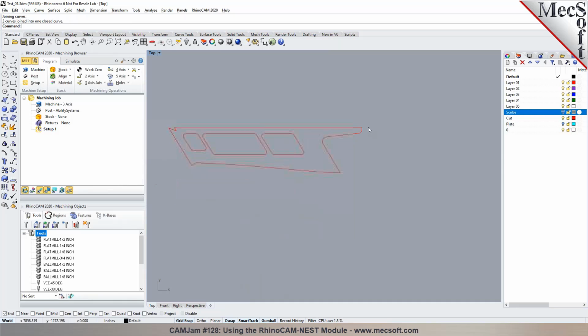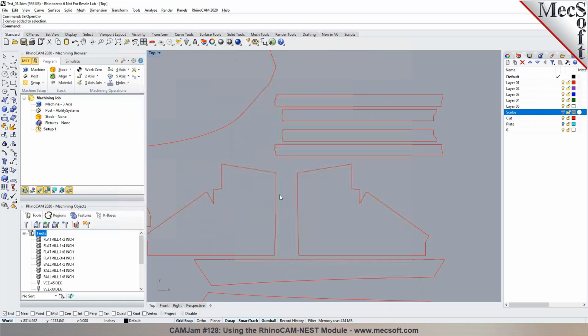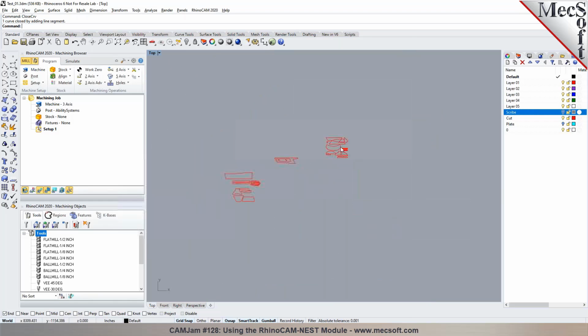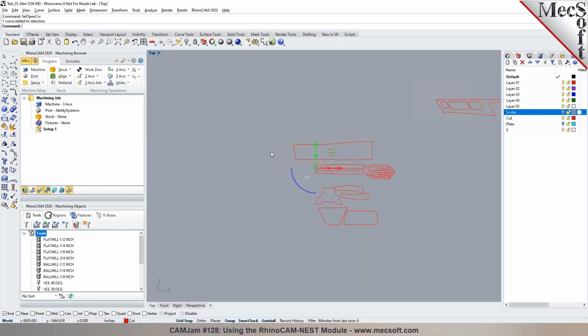All right. Yeah. So let's go ahead and check again for open curves. What we are doing right now is, you can see again you have some issues in here, right? Yes. You can see those verticals are probably double lines. Yep. So I just did a close curve command in Rhino to close it. Now if you do a select open curve command in Rhino again, it's still finding an open curve right here. Okay, this is the one. You can delete that one, yeah. For now, we'll just clear it out.